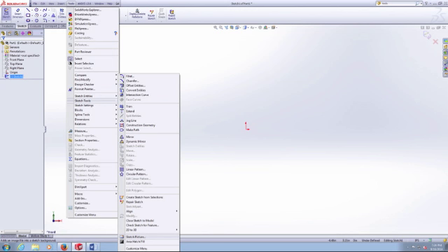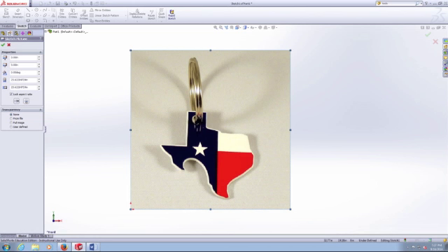In the Tool menu, open Sketch Tools and select the Sketch Picture option at the bottom. This will bring up a Document Explorer window where you can browse and select your image. Once you've selected your image, it should paste right onto the plane that you've selected.